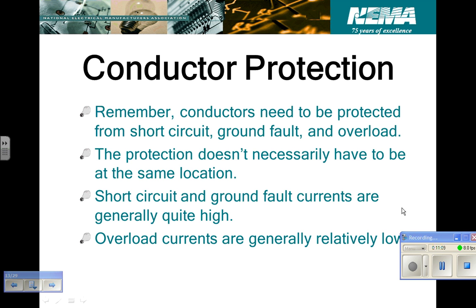So we're really talking about three different things here. The short circuit is protecting the conductors, period. Stop. Okay? I don't want you to get confused about these things at all. I want you to be very clear about these definitions. Short circuit, you're protecting the wires. Stop. That's it. Ground fault, you can't really protect against that in the motor situation, can you? And overload is generally not taken care of by the fuses or the circuit breakers that protect the branch circuit conductors. It's being done by the motor starter and the overload block.